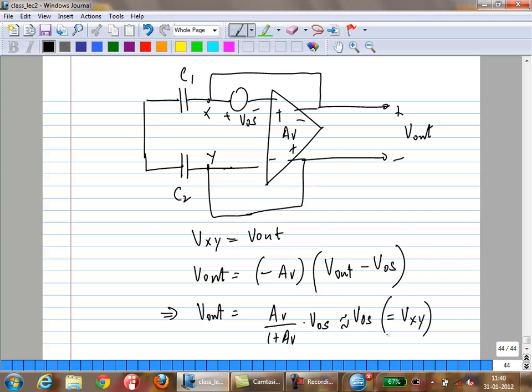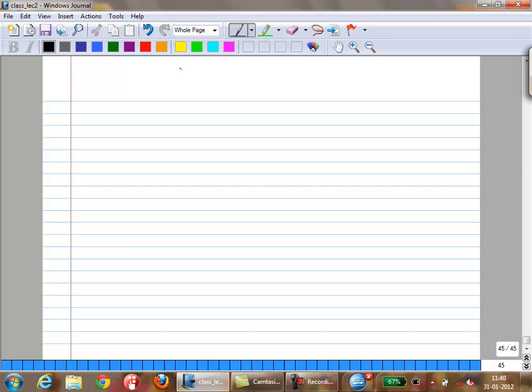So remember, I think did we talk about this? The fact that capacitors always come with their own parasitics. If you take any IC capacitor, you'll have parasitic capacitance to ground from here, parasitic capacitance to ground from here. Okay, and typically the bottom plate will have larger capacitance. So if you have a capacitor like this, the bottom plate is closer to the substrate, so it has larger capacitance. So if you have the signal coming in here, you're degrading because you're losing some of the signal to ground. Okay, so now you want to get rid of these capacitors in the signal path. Okay, so that's what you want to do.